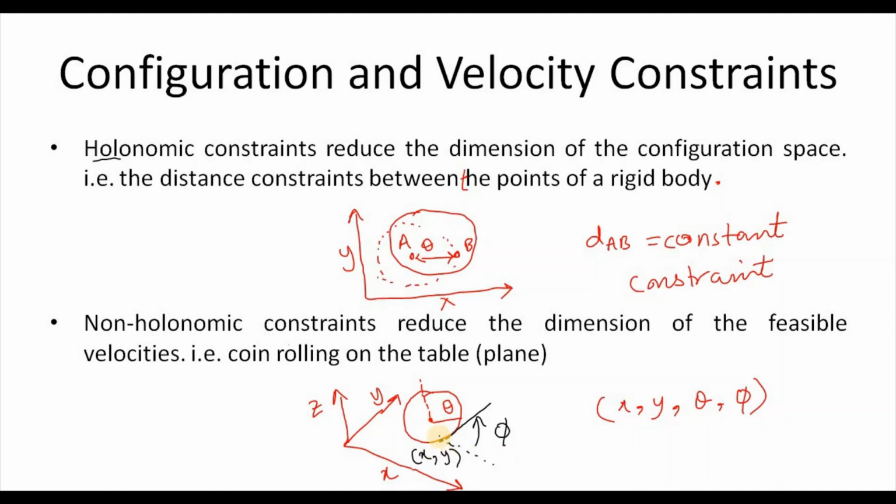and then you can have a velocity along the x-axis. So here you have noticed that although this coin can reach anywhere on a rectangular two-dimensional configuration space, it has some velocity constraints that limit its velocity along certain axes. These types of constraints are called non-holonomic constraints, and they're also called velocity constraints.